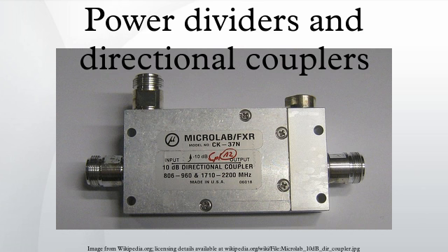The resistors in the bridge which represent ports are not usually part of the device, these being provided by the line terminations. The device thus consists essentially of two resistors. Applications. Monitoring. The coupled output from the directional coupler can be used to monitor frequency and power level on the signal without interrupting the main power flow in the system.